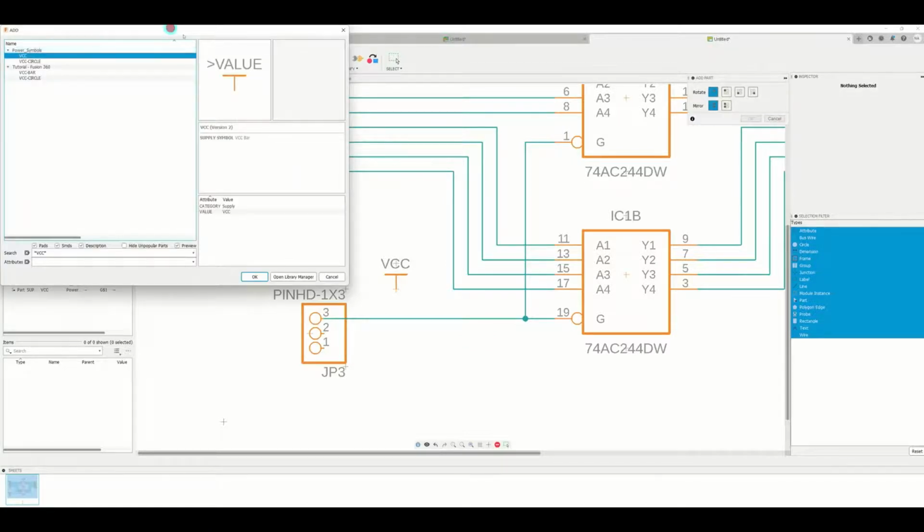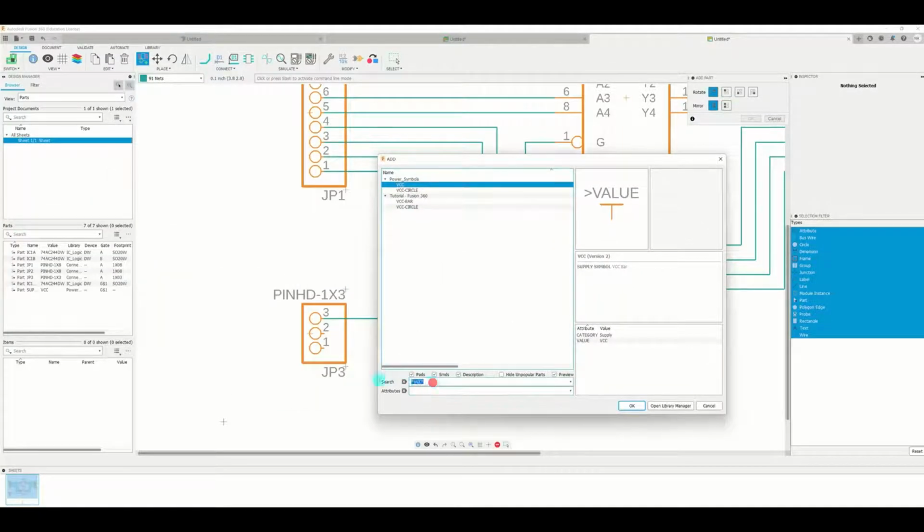So this time we now type ground to find ground. So asterisk GND, ground line. You can use that one or this one or this one. Most of the time we use this in our symbol, but really this is a ground to earth, meaning the pins are connected to the casing of the board, but sometimes you don't connect the ground to a plane, so you can select this ground one or this one, and then you put a value of GND.